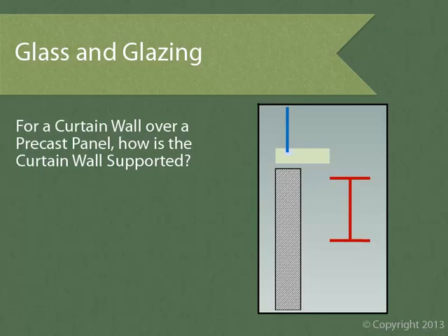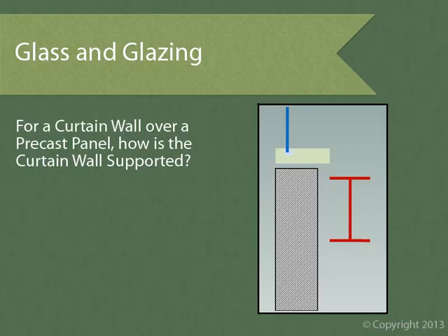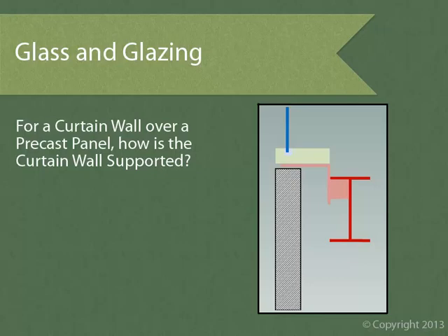Precast systems are routinely designed by the design-build precast subcontractor to support their own weight and nothing else. And we have two options for this condition. We could increase the structural capacity of the precast to support the curtain wall load. This will probably also mean adding embeds in the top of the precast panels for attachment of the curtain wall. Or, we could provide a steel ledger angle to bridge between the building structure and the sill mullion. Because precast engineers are usually very apprehensive about having another sub's work bear atop their panels, this steel angle is the route most often taken.